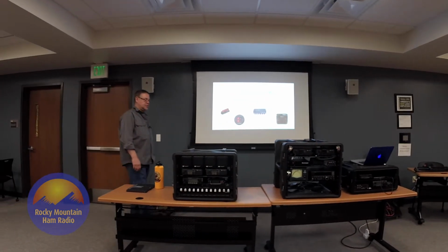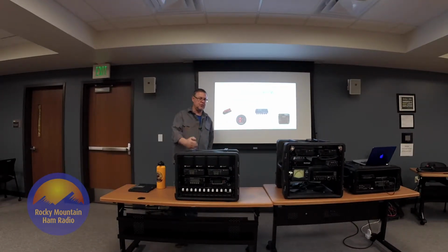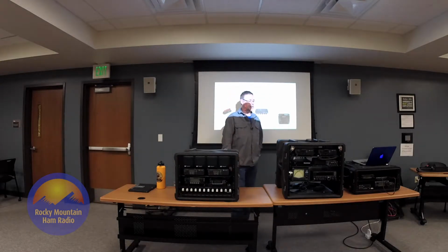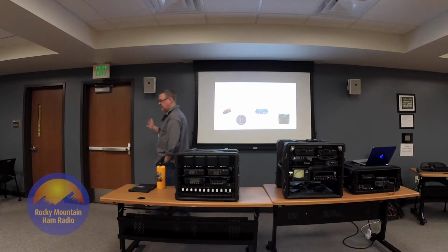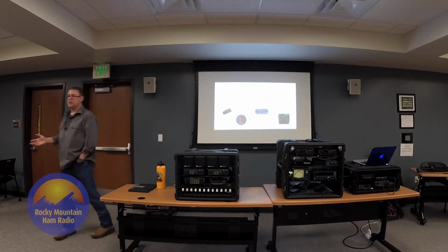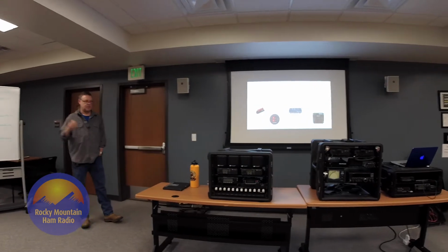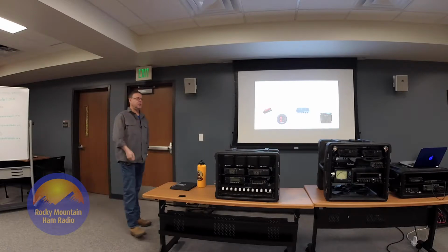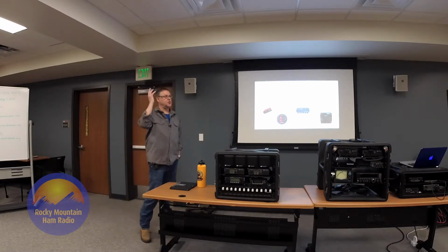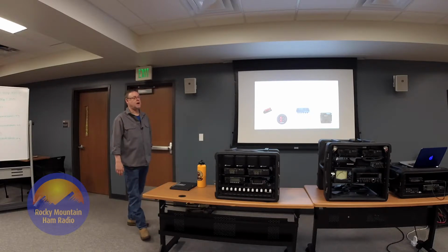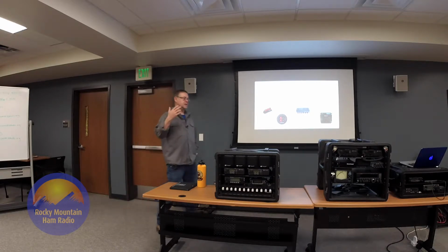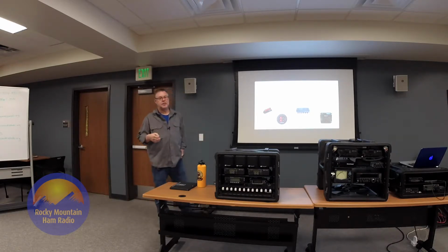But other items on power management: fuse everything. And bring spares. Bring lots of spares. Gensets on command post incidents, whether they're planned, whether they're natural or whatever, get power bumps and power spikes continuously. People plug in, unplug, the generator idles down, the school has a brownout for a second or has a spike because a power pole just burned down, feeding one of their grids. Whatever the case may be, your power quality is an issue.